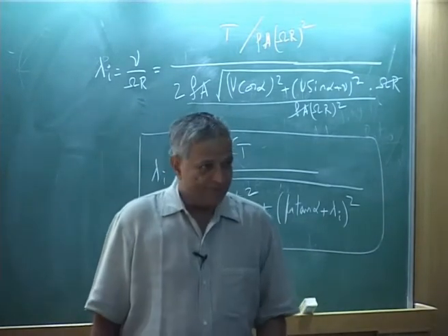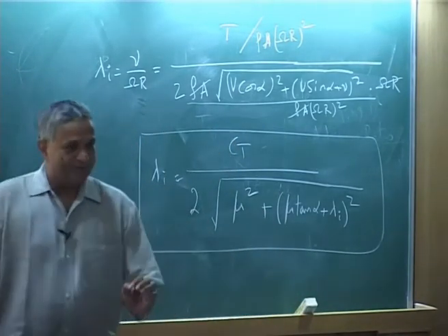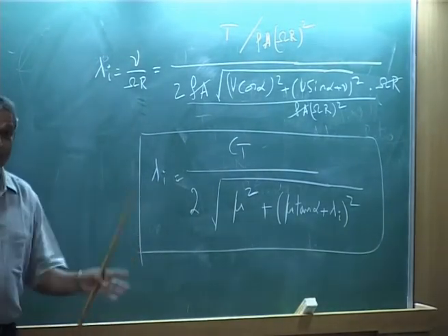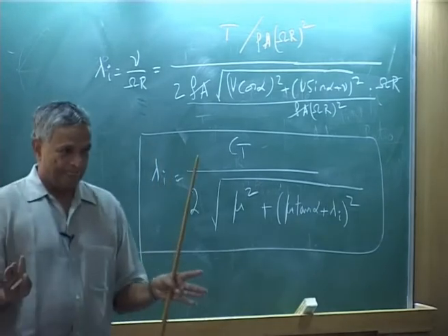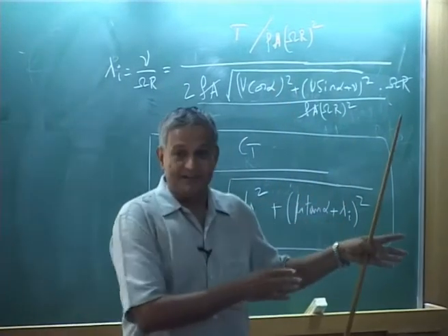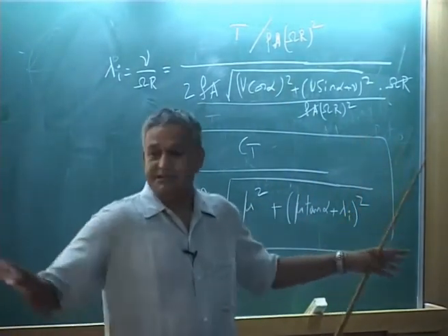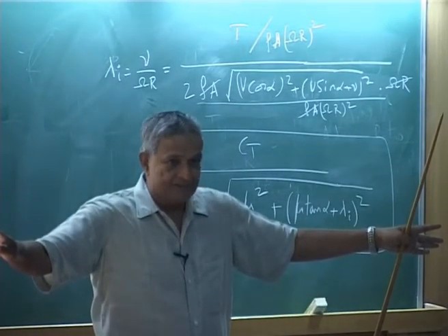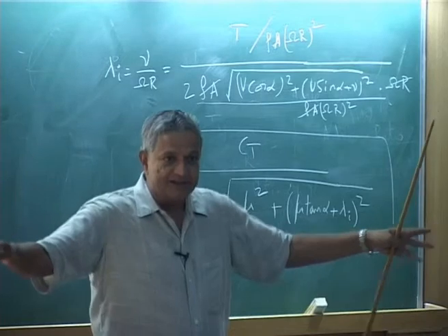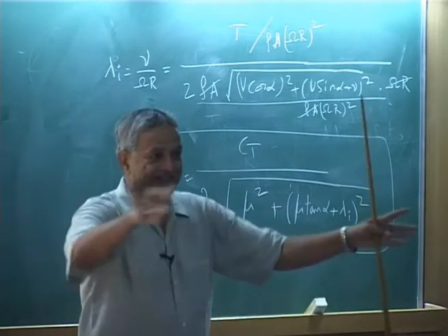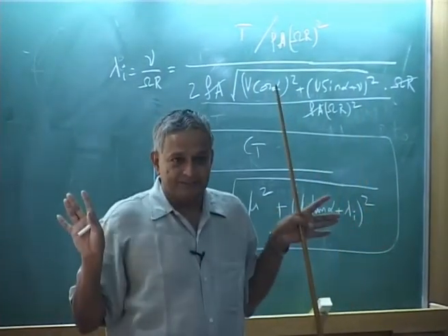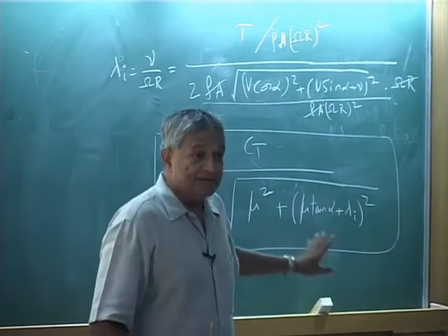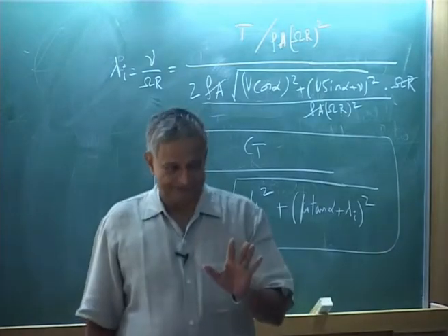Okay. Now, forward flight, the moment you go to forward flight, all this comes, and this inflow is a gross approximation of what really happens on the rotor disc, because you have assumed that it is constant over the entire disc. Please understand, it is uniform everywhere, but this is a gross approximation, and this is still used.